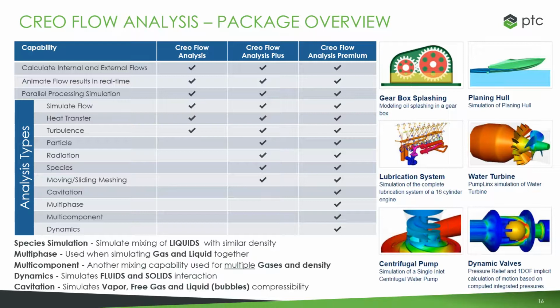I think it would work fine. It does do multi-phase, so I think if you get cavitation, it will show you that. It will show vortices in general. And it's just a case of putting the right pressure on. Now, it doesn't care whether pressure is positive or negative. It'll handle it. But if you're dealing with very low pressure, then cavitation is the issue. It will do it nicely.